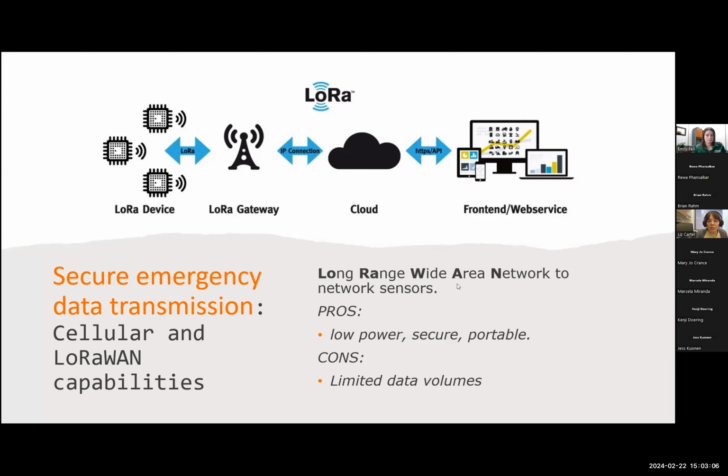So we generated these flood maps, and if we are actually in a disaster event, we have to be able to get the data off of our sensors fairly quickly, and we have to be prepared with a little bit of redundancy in case cellular networks have gone down. So our camera-based sensor nodes have all been equipped with the ability to send the data out to a server using either a cellular antenna or a LoRa antenna.